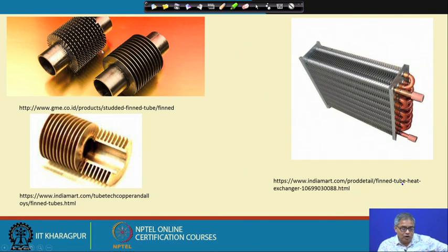Now, these are small pieces of tubes. In a heat exchanger, how it will be put, one can see. So, these kind of heat exchangers are very common in refrigeration, air conditioning and cooling application. So, one can see that a tube in serpentine way it is entering, it is starting from here and it is ending probably at the top. Fluid can enter from here and fluid can go out through this, while having a very long journey through the tube. While it is having a long journey through the tube, it will exchange heat with the gaseous fluid